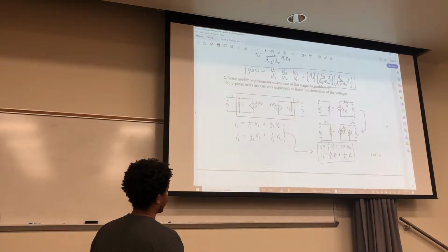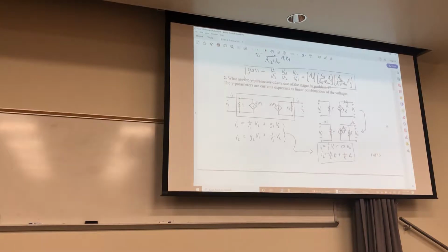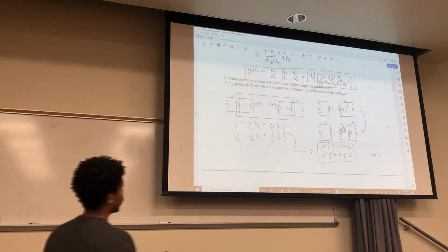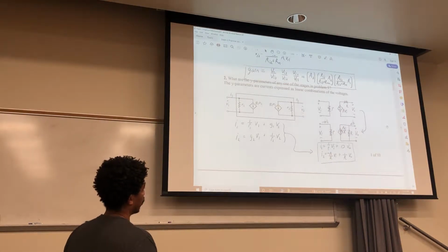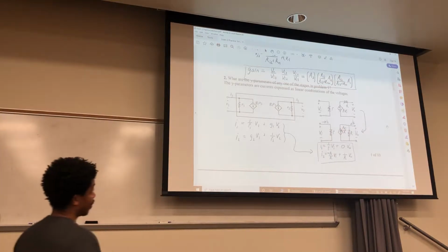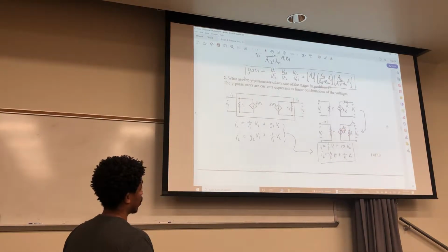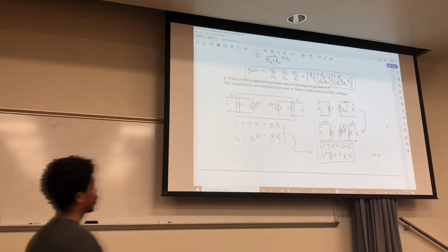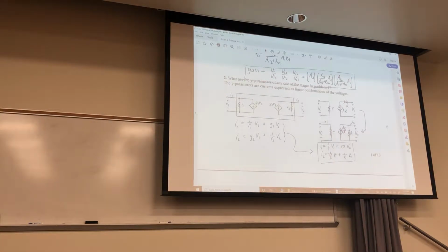So this is Thevenin form, and this is just Norton form. To go back and forth, the resistances are the same, but for the voltage and the current, you just convert them using the resistor. This is in terms of voltage. To make that in terms of a current, you just divide it by the resistance. If you went the other direction, and that was in terms of a current, then you just multiply by R to get the voltage, and that would be your new voltage. And then looking at it from the outside, you can't tell if the inside of that black box is a Thevenin or Norton. They behave exactly the same.